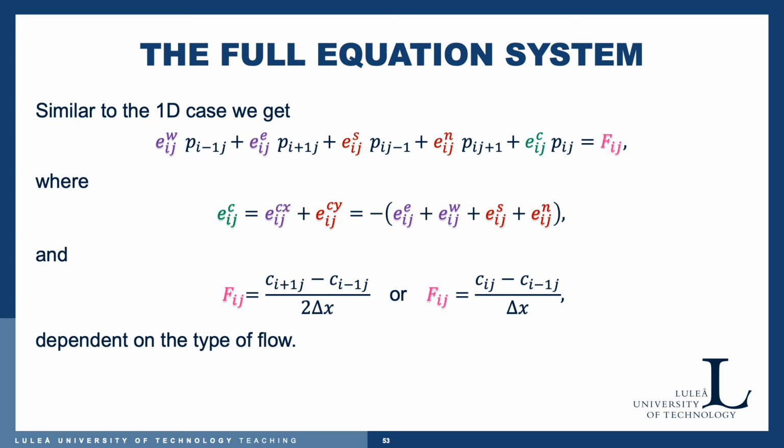And the right hand side, the discretization of this one depends on the type of flow, or the type of situation we apply this type of equation to, but in terms of the Reynolds equation, it's a type of flow. And the central one is okay as long as we don't go from elliptic to hyperbolic within the region, and if we do, we have to consider instead an upwind discretization scheme.